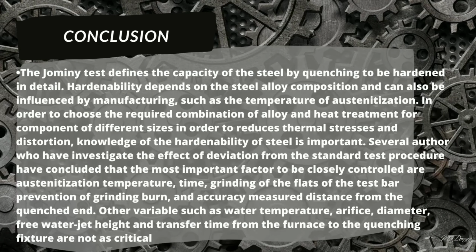So, in conclusion, the Jominy test defines the capacity of the steel, by quenching, to be hardened in detail. Hardenability depends on the steel alloy composition and can also be influenced by manufacture, such as the temperature of austenitization. In order to choose the required combination of oil and heat treatment for components of different sizes, in order to reduce thermal stress and distortion, knowledge of the hardenability of steel is important.